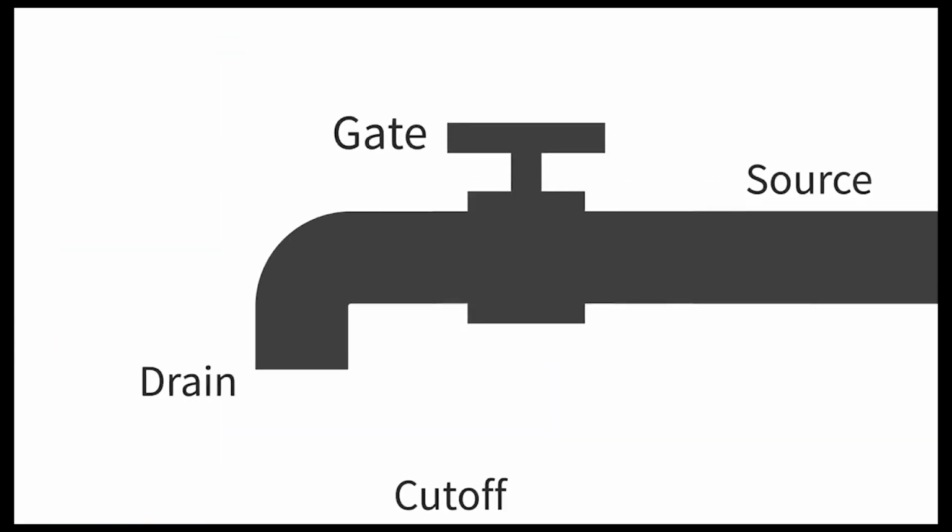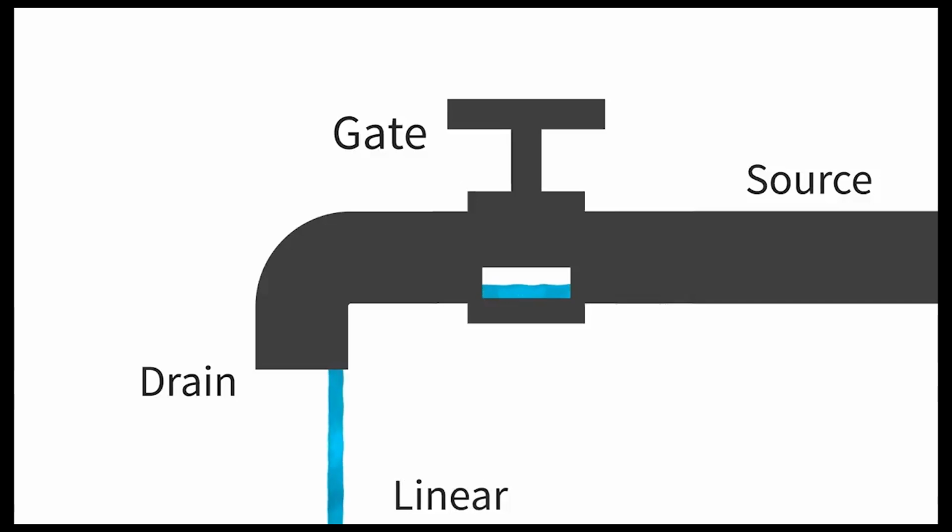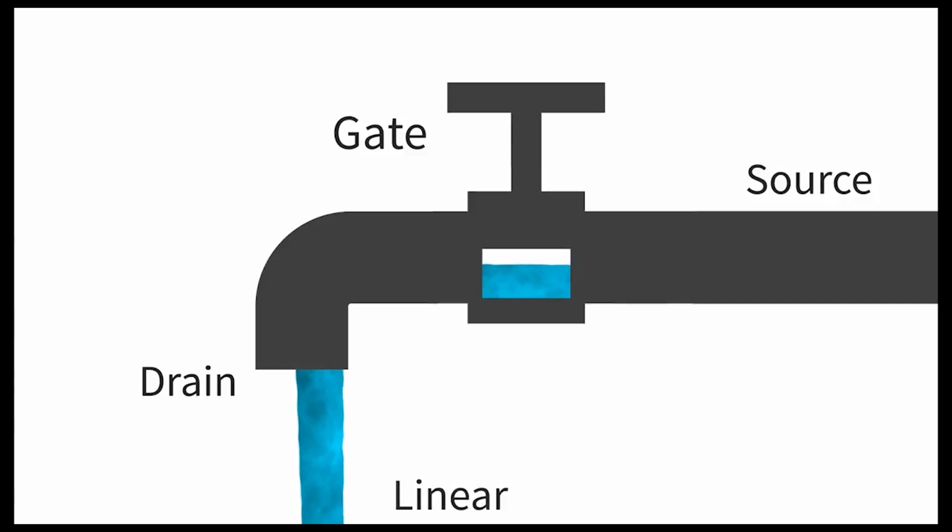The gate voltage is opening the tap, while the drain source voltage is the water pressure. As you open the tap, no water will flow until there is water pressure. And if the tap is open and the water pressure increases, the flow will increase linearly for a while in the linear mode until no more water is capable of leaving the tap, at which point it will be saturated unless the tap is somehow opened even more.